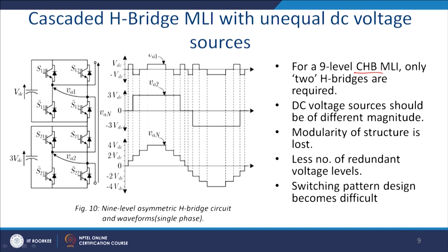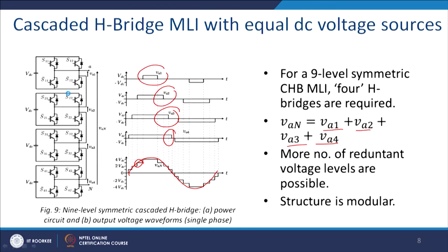cascade multi-level inverter. Here is a special case, we can switch in such a way, if it is allowed, plus and minus. In the previous case you see that you have applied only positive voltages. Thus, one combination of switching is being used, and we can generate negative voltages by it and increase the number of switching states by simply changing the controller pattern.